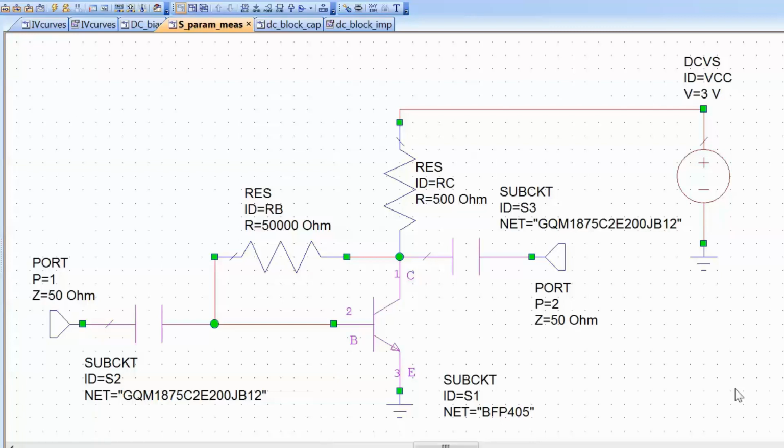And the other one is for your RF, your high frequency signals, to flow back into the bias network and up to the power supply, because this would then create a modulation of your DC bias, and it would not just create a bit of a mess with the stability of your DC bias, but also create some considerable losses in your RF performance. So how do we achieve that?